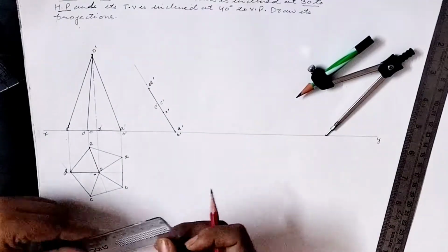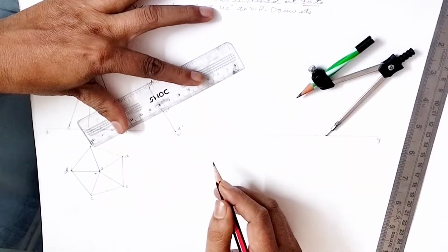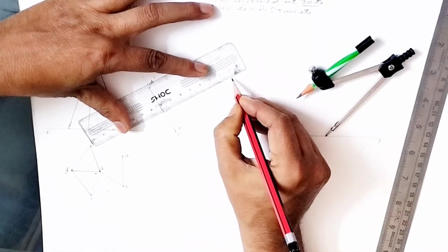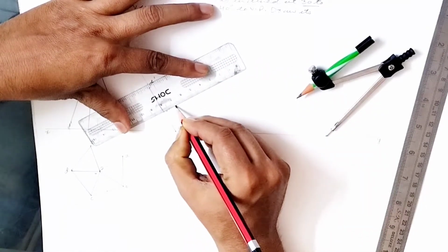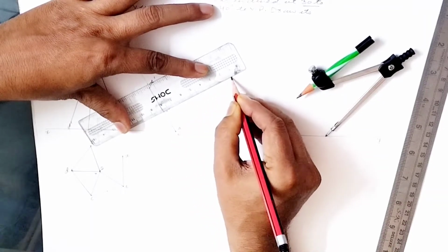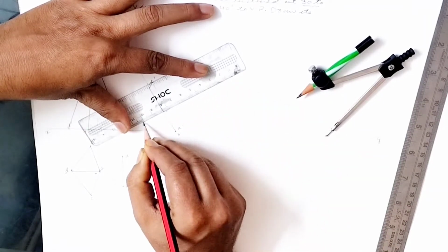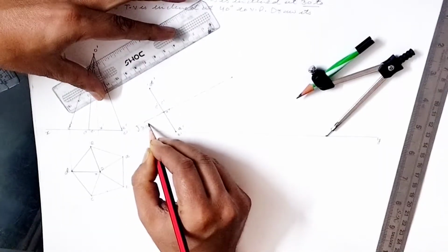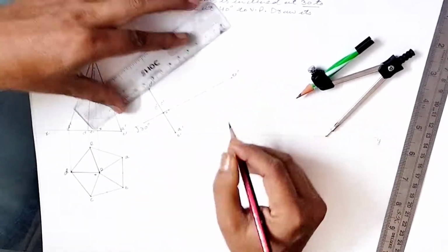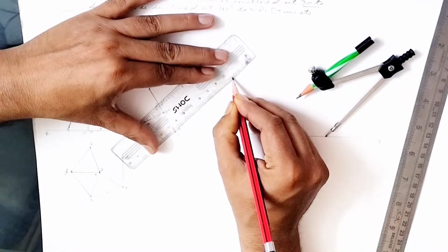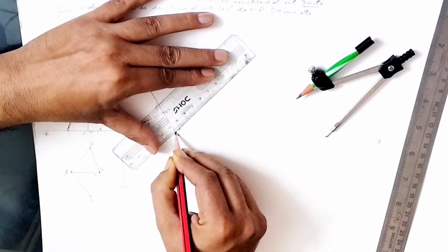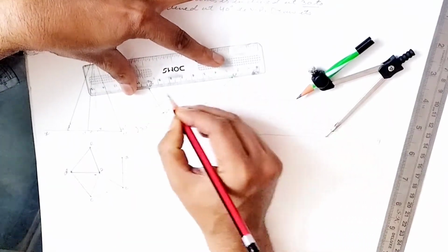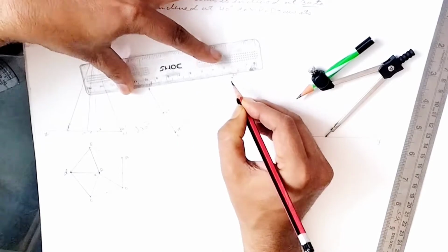Now we can see that the central axis is perpendicular to the base. So from the center, draw the central axis by keeping its inclination at 90 degree with the base and extend it up to the reference line in the back side. So this angle is 30 degree, which is given in the problem. So again, join all the points of the base with the apex and make the outer boundary always dark.